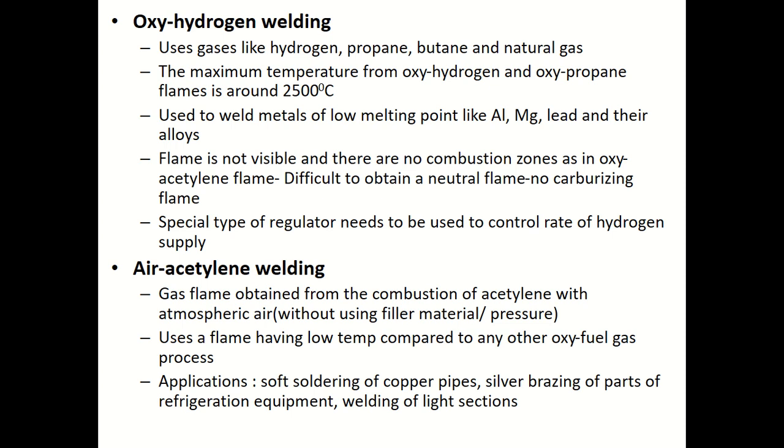And what is air acetylene welding? Another type of gas welding. The gas flame is obtained from the combustion of acetylene with atmospheric air. Here you are not using a filler material, or applying any external pressure. It uses a flame having low temperature compared to other fuel gas processes. And what are the applications? It is used for soft soldering of copper pipes, silver brazing of parts of refrigeration equipment, and welding of light sections.